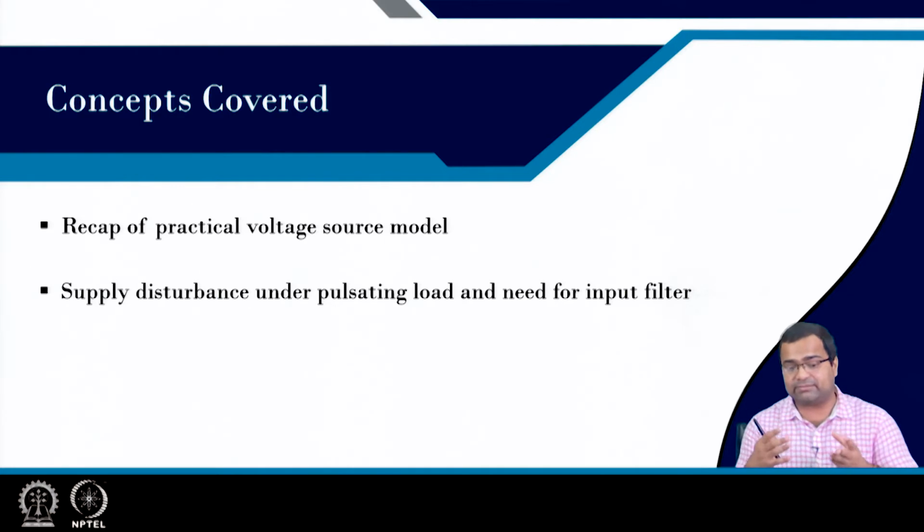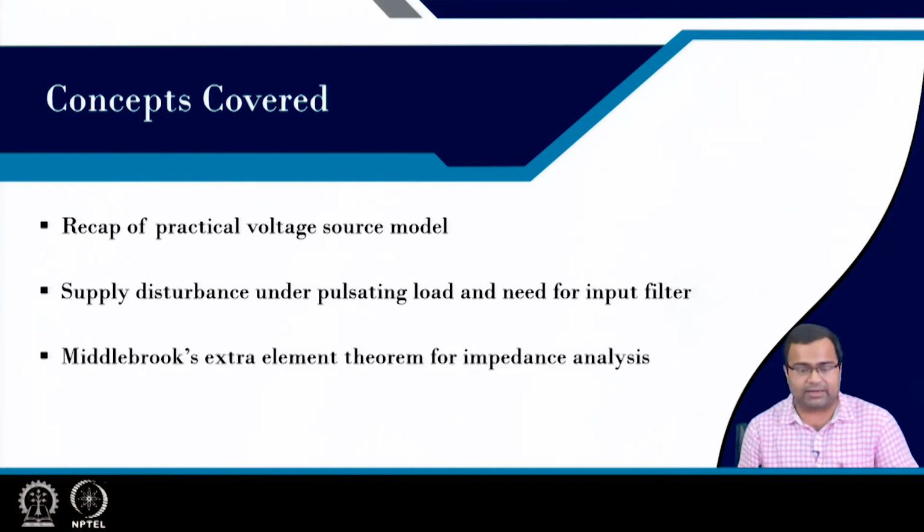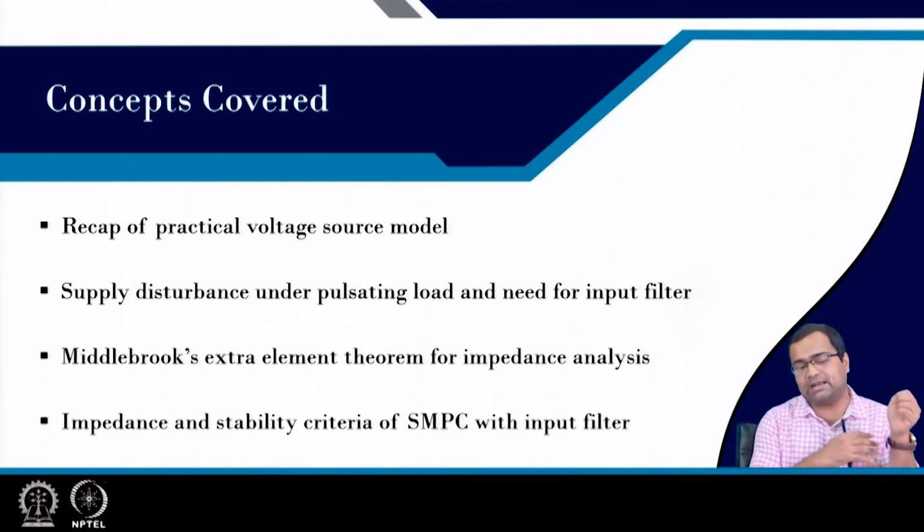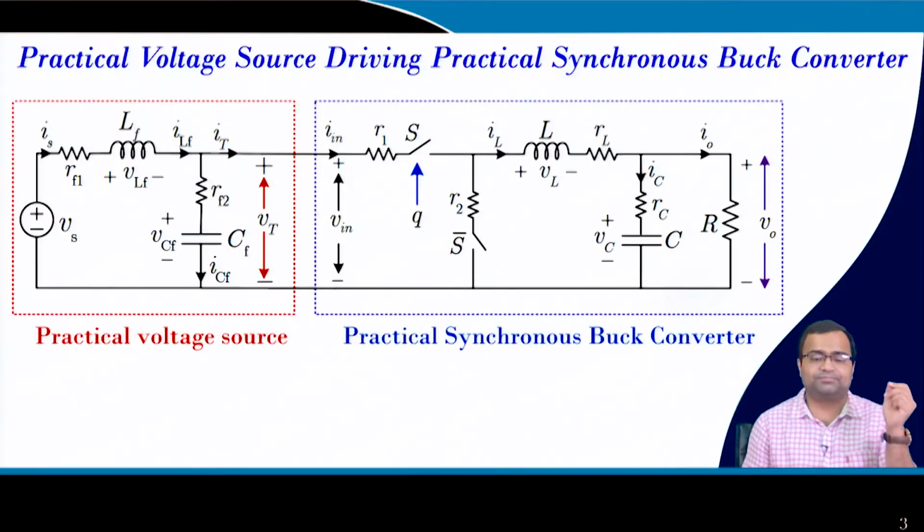Then we want to again demonstrate the supply disturbance under pulsating load, and then we want to identify the need for an input filter. Then we want to discuss the Middlebrook extra element theorem for impedance analysis with input filter, and then impedance analysis and stability criteria for a switch mode power converter with input filter.